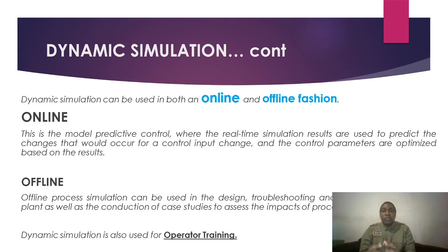Scenario number two, when you are building a new plant, you would want to virtually commission your design before building a physical plant. In the sense that maybe after applying steady state simulation in the initial stages of the design, you then go a step further to enhance that steady state simulation to come up with a dynamic simulation which gives you a prediction of how your system that you want to construct will behave with time, right?